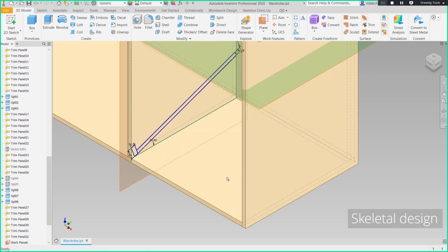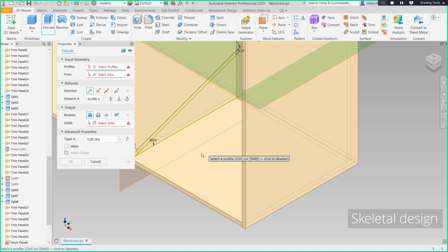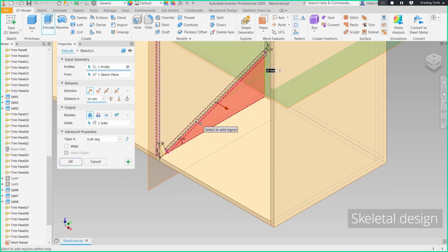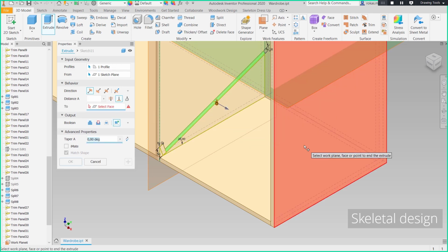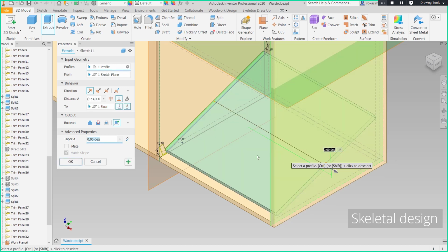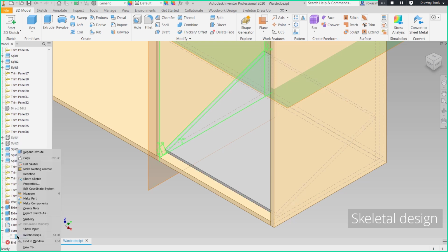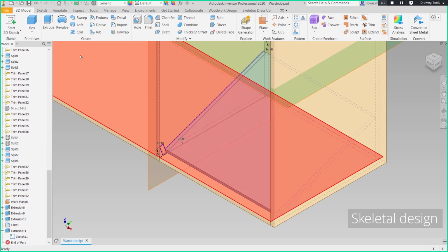And then just make a new solid, which will then later be translated into the new part and then combined in a new assembly. So we can define the size of the panel by just indicating the limiting factor, which in this case will be another side of the block. And then later this sketch can be set visible one more time to use for the next operation.